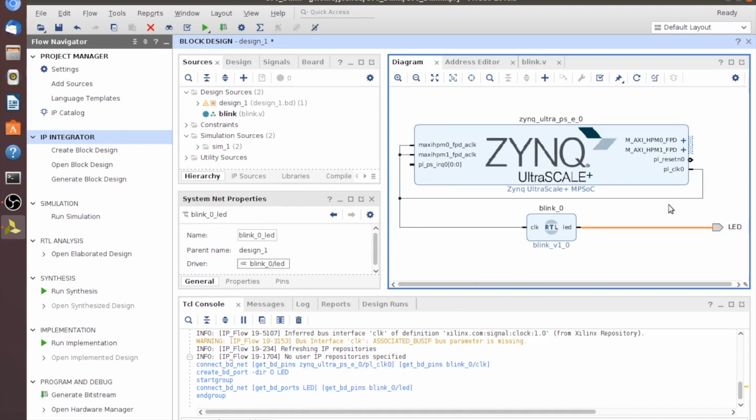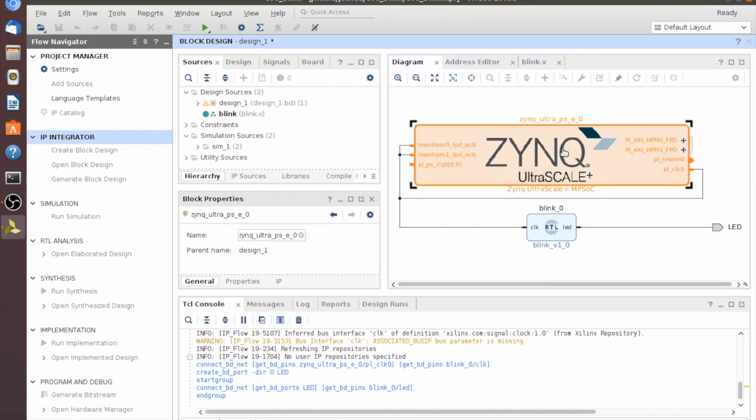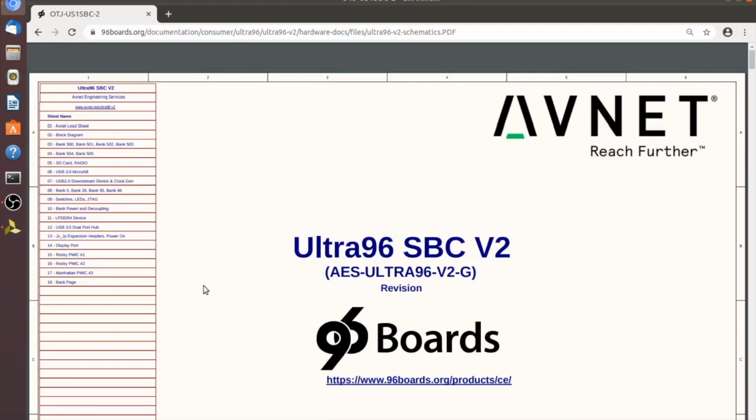Now what we want to do is make sure the pin that we want to use for this LED, which I've decided is going to be, I guess, pin 3 or D7. Pin 3 on the low speed bus, or D7. So what we want to do is find that pin and how it's physically connected in the FPGA. So I'll open up the browser and take you to this page, and I'll put this link down below. So what you want to do is find the actual header, the low speed header.